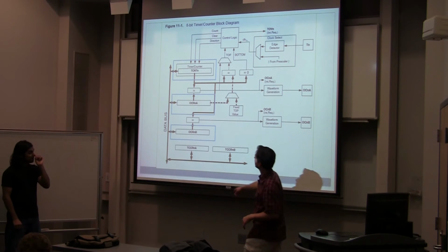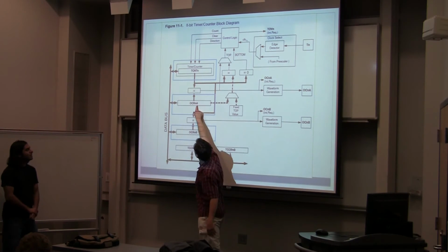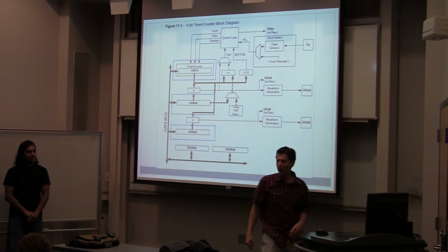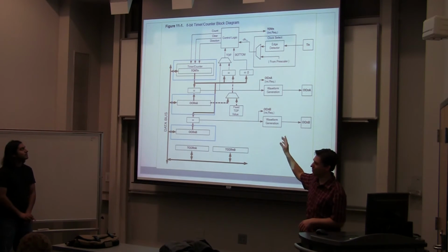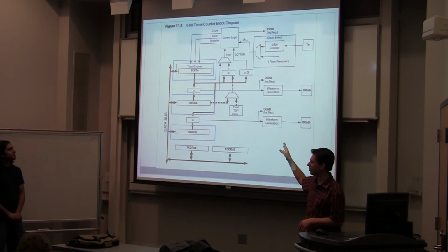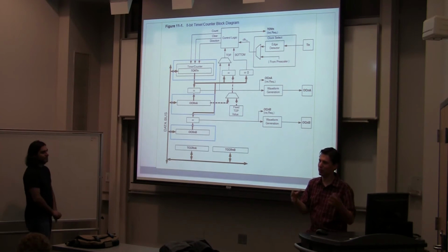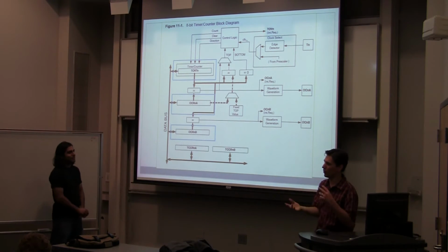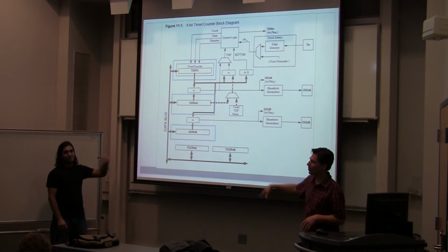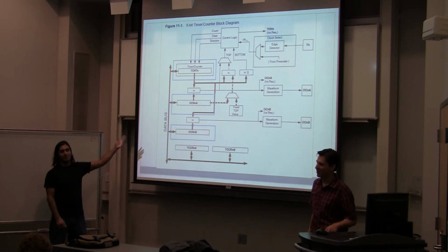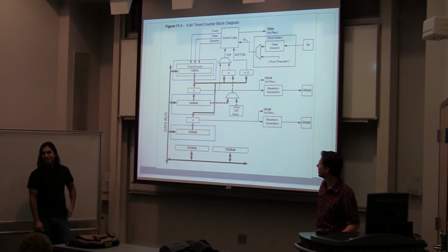So yeah, you'll notice they all have these little ends. That's just the way that the Atmel data sheets refer to different ones. Like if n is 0, if you have TCNT0, that refers to your timer counter 0 module. You have two: a timer counter 0 and a timer counter 1. So this is basically just their way of not having to put two diagrams in for two completely identical timers.